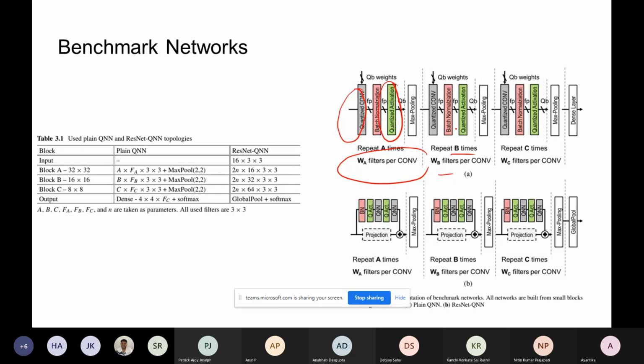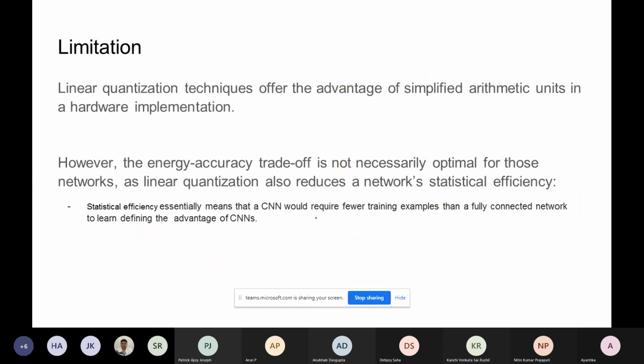Of course, there is some extra overhead to add that hardware, because that is also operating and consuming some amount of energy. But overall, since you are working on a lesser number of bits, when you had your inputs as m bits and now you are working on q bits, where q is less than m, your MAC module is working on fewer bits. There you are gaining in terms of overall energy consumption. So this is about what we discussed on training and testing quantization.